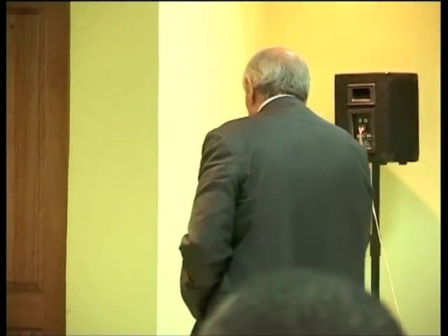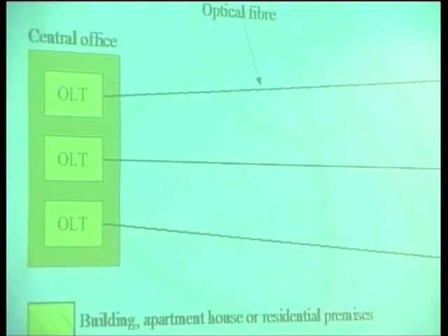This is the point-to-point architecture for the optical distribution network. As you can see, any customer, which means any ONU, has its own fiber and its own OLT in the central office. Of course, since you have no splitting at all, the optical loss will be confined to the loss of the fiber. Even if you have a 20 kilometers fiber, the optical loss will be 8 dB or less. There is no resource sharing. Any customer gets its own link.